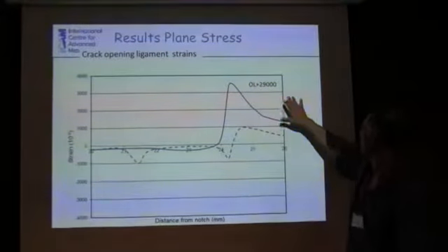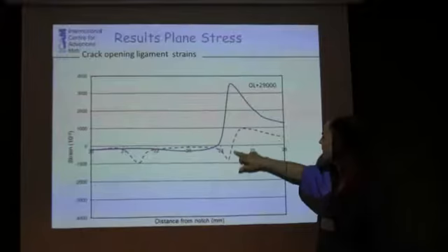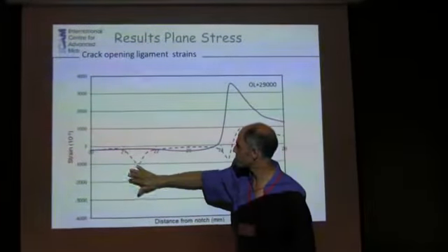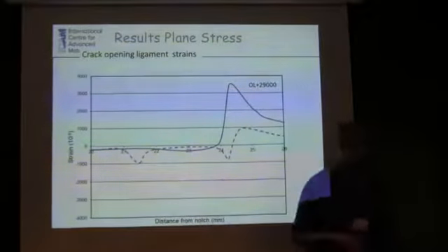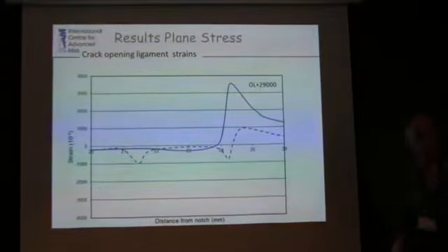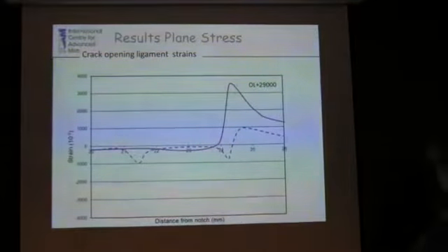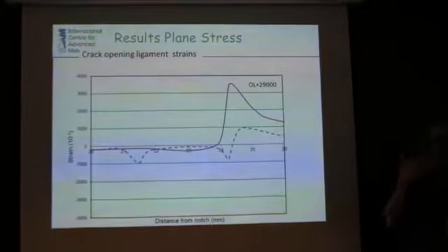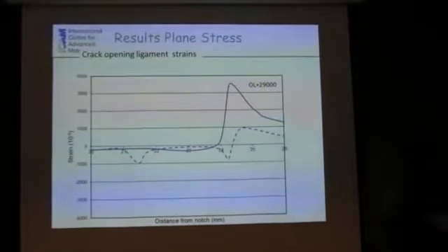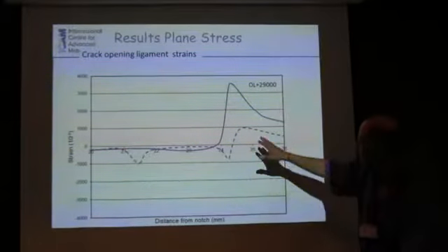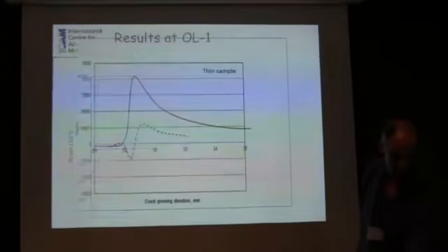And then eventually, this is 30,000 after the crack. You still see the plastic zone here, but you still get this compression. This is an elastic compression at the crack overload position. So I'm not sure whether I agree about whether you get plasticity-induced closure of the traditional kind, but you certainly get what I think Norman Fleck would call discontinuous closure. Closure forces far away from the crack where the overload occurred.